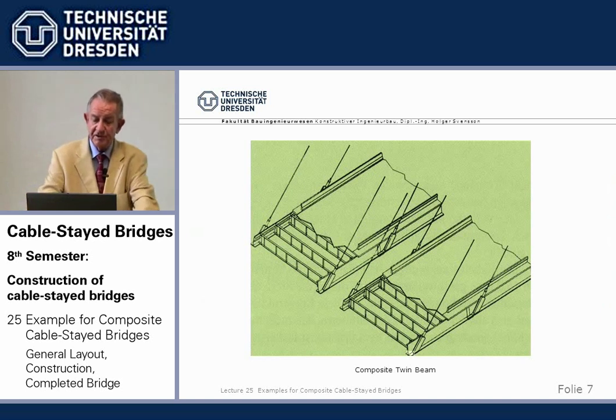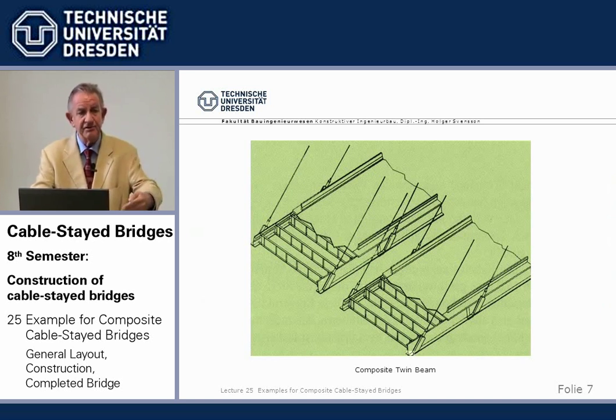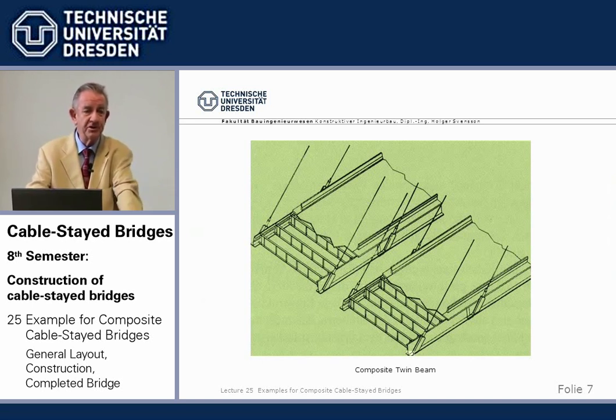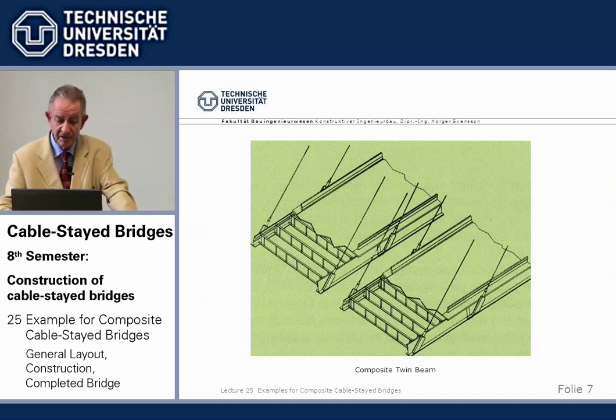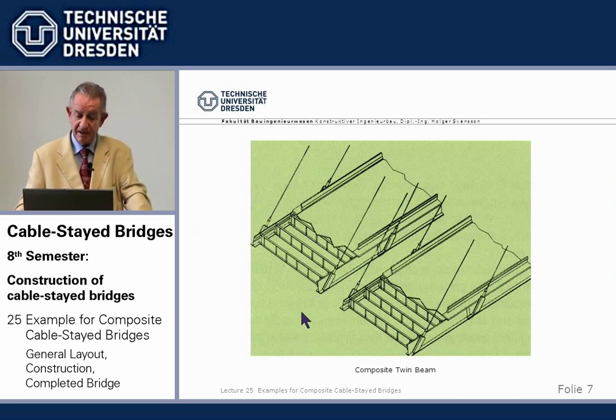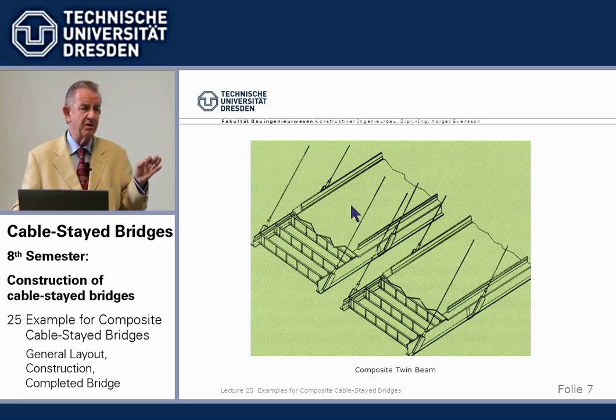I said 2 separate beams were the most economic solution. And since we were given, so to say, the steel alternate, concrete was with the competition, Jean Muller, we said, okay, the good principles we had established for Sunshine Skyway, we use a steel grid with open sections, and we use as a deck, not an orthotropic deck, but concrete. Remember, no site welding in the United States, only bolting.